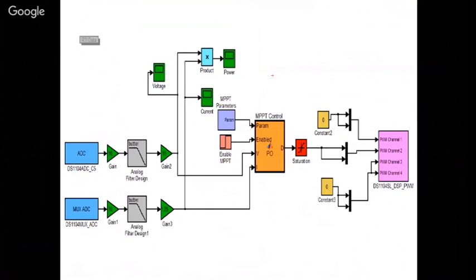This P&O block yesterday I showed you in simulation. With this P&O block yesterday we had the PV panel connected, we had the load, everything. So when you want to implement in real time, you take only the control circuit; all the power circuit you have to remove. You have to just remember this. Because the power circuit cannot be embedded in a controller. Power circuit is a very high voltage thing. How will you embed it? So only the control circuit.